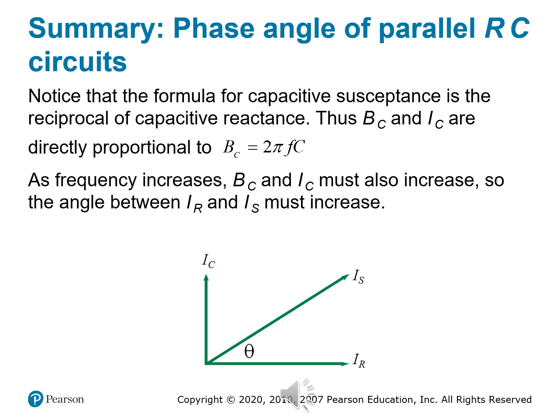Let's talk about the phase angle. It's not just some number, it gives you a visual cue. If you look at I sub R, from the resistor's point of view, that stays steady. I sub R is on the horizontal real axis. Resistor, real axis.